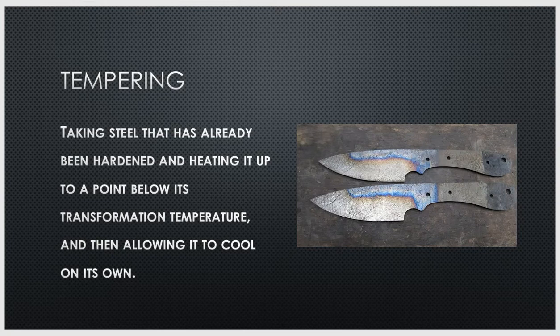When you harden the steel that you're using for your blade, you're hardening it because you don't want your knife to break. You want it to be hard, be able to pierce things, but then you also want to temper it. That way, if you're moving it around, using it to cut something tough, or you need to strike an object with your blade, you don't want that piece of metal to shatter into a bunch of different pieces.